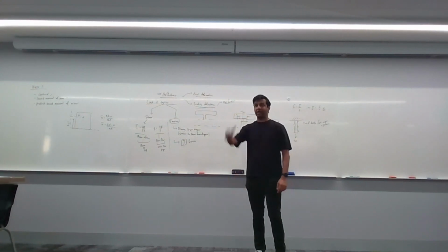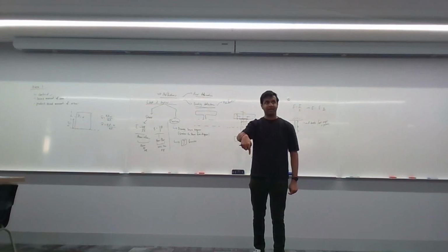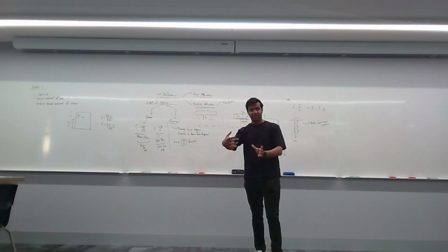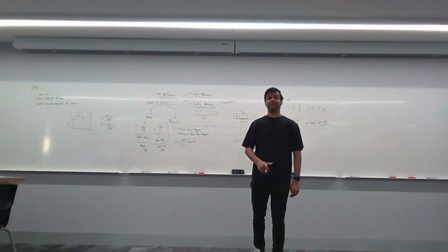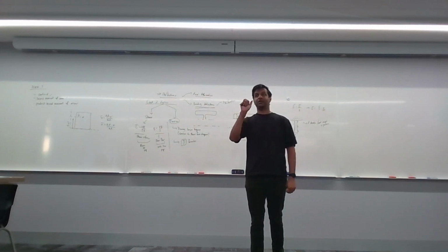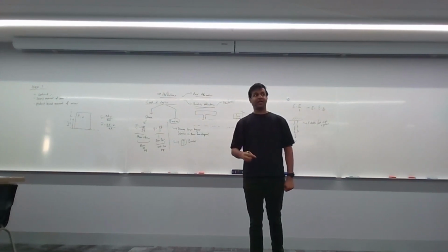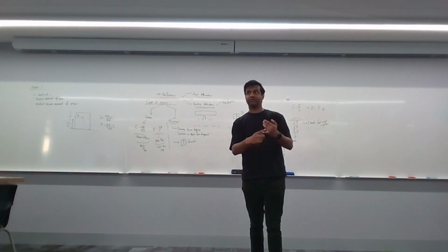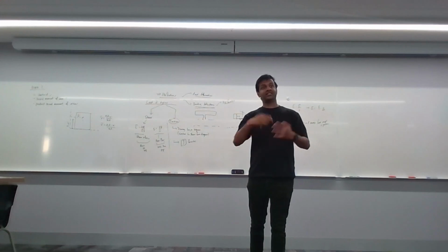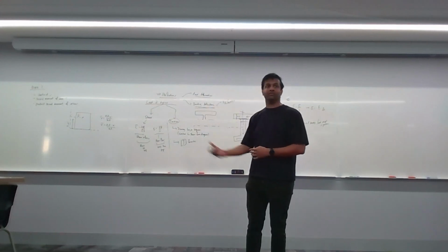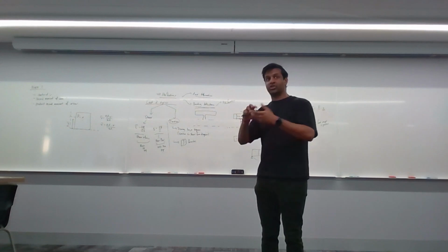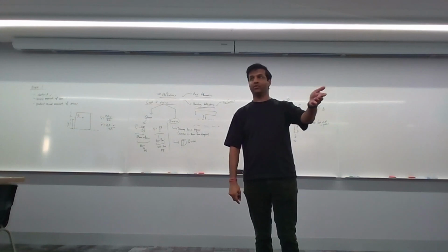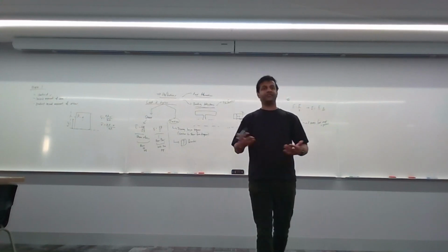And I apply a downward load on it and I twist it at the same time. What's happening? I'm inducing shear stresses on the outer edges and I'm pushing down the bollard, which means there are two stresses that it's experiencing. Normal stress and shear stress. Now, what's stopping you from drawing out a Mohr's circle for that question? Because now you have a combination of shear stresses and normal stresses. That's a possible combination for you to be able to tie in your shear stress understanding from torsion all the way to the Mohr's circle type question. In fact, that's in one of the workshops, in the last workshop. So have a go at these different types of questions and practice.